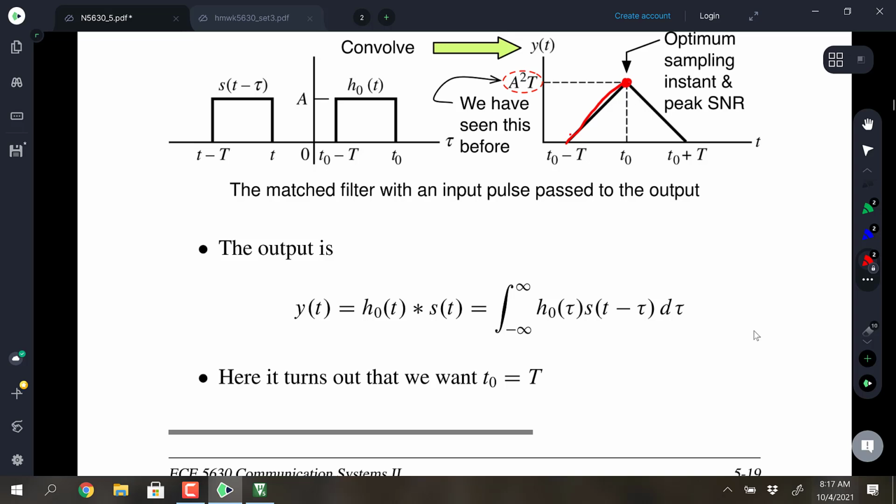So that burst would come back, and then you would filter that signal in the receiver with this matched filter, and then you would time it to look for the maximum deflection and sample that, and that would be your target present, target not present type of scenario. So that was really an on-off keying situation. I'm not a radar expert by any means, but does that sound reasonable from a modeling standpoint?